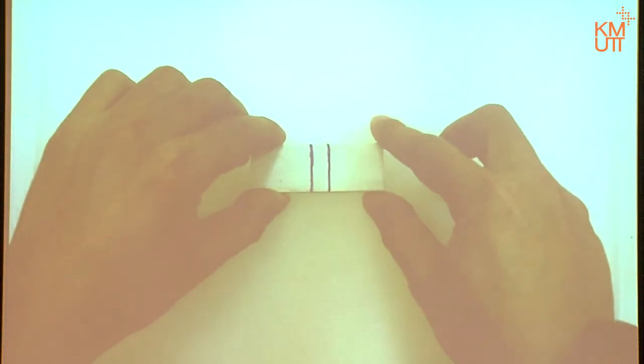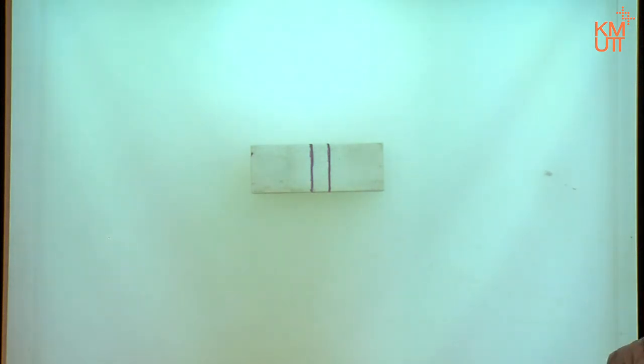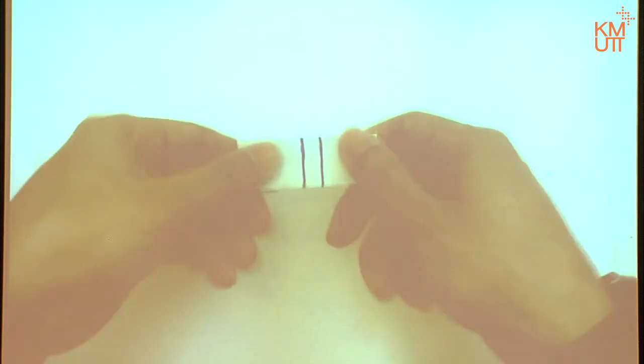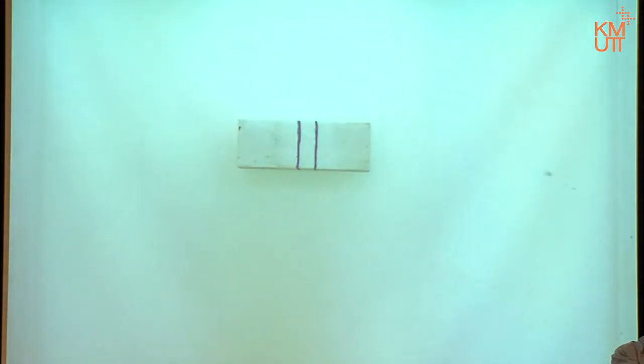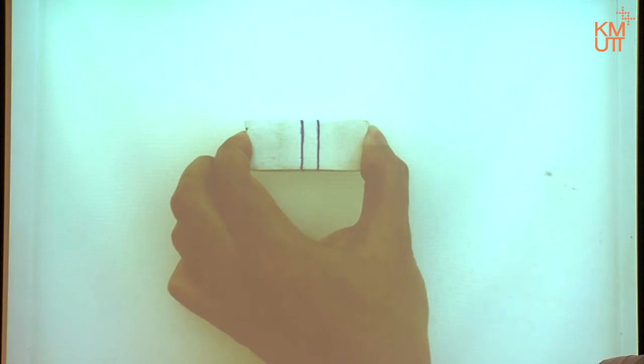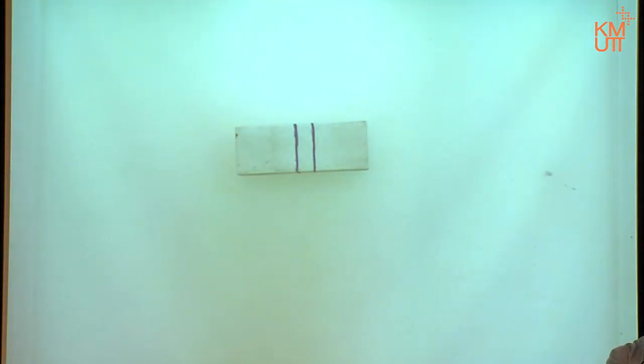Okay? The first internal force that we're looking at is what we call axial force. Okay? There will be the letters showing later, axial force. What it does is that, looking at these two lines, the force will be on the line of the member. Okay? Then if I pull them apart, notice these two lines, they move out. If I actually press it this way, then these two lines get closer. Correct? These are the mechanism of axial force, meaning it makes the cross sections go away from or into each other. Okay?